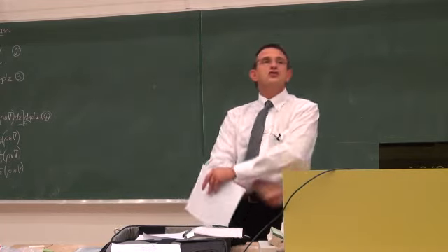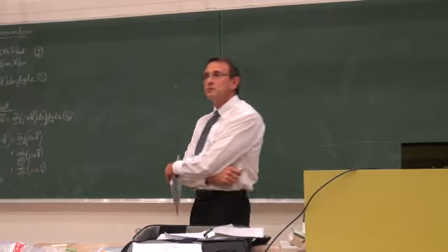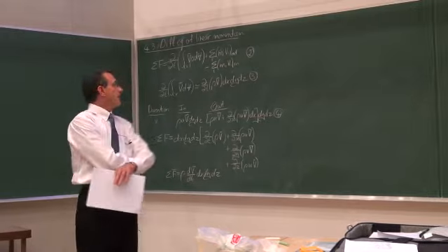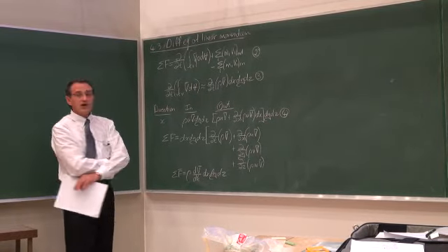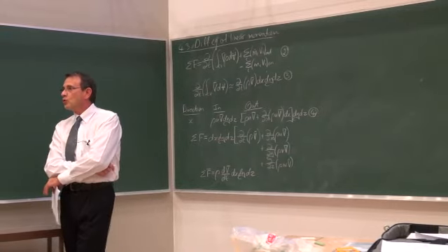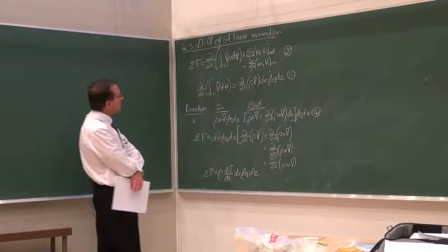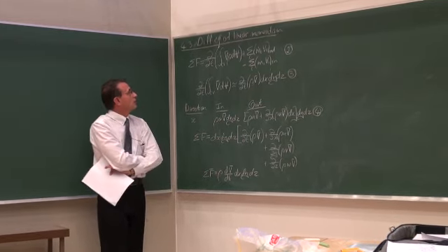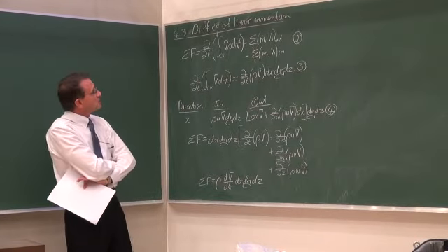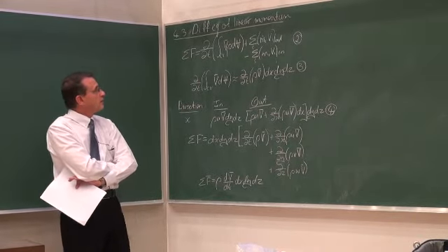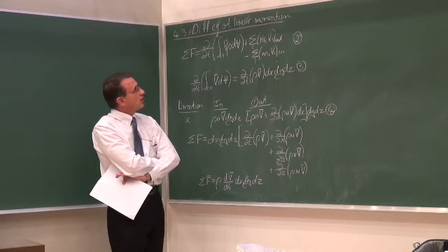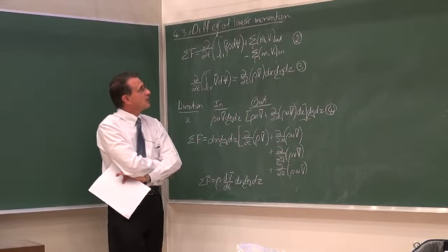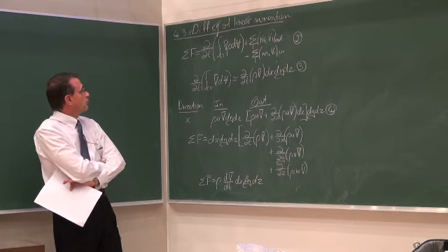Let's just revise quickly the most important work that we've done in the previous lecture. We started by looking at a control volume, and in this case we are interested in forces because Newton's law is all about forces. So we said that the sum of the forces is equal to partial d/dt of the control volume integral of the velocity vector times rho dV, plus the sum of the mass flow rate multiplied by the velocities going out minus what is coming in, and that would be the sum of the forces.